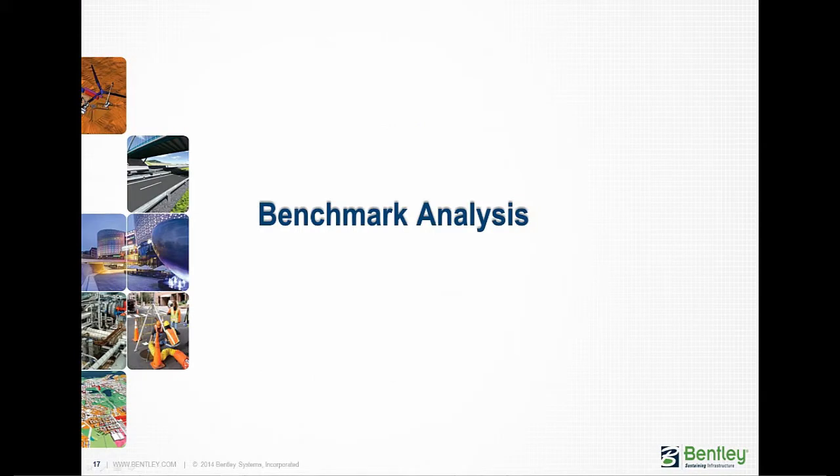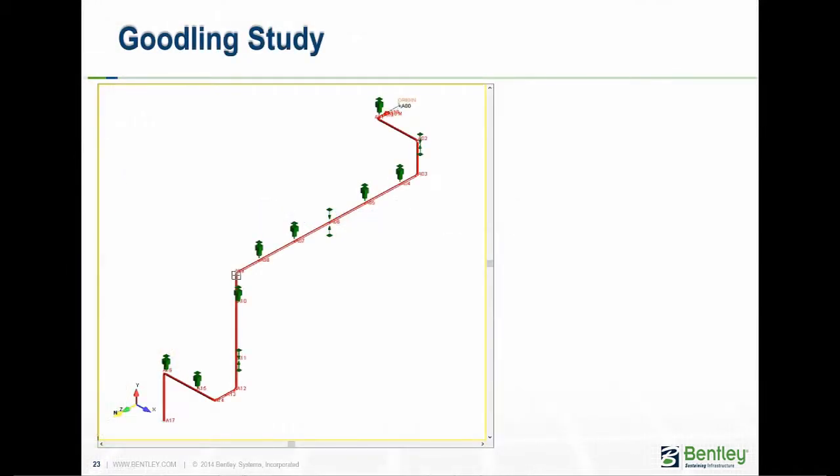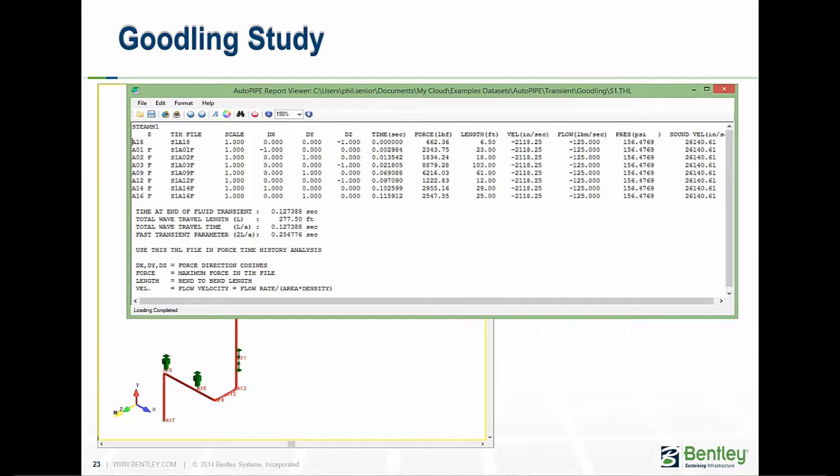In the early 80s, Goodlin investigated steam hammer in power generation plants. Whilst this flow condition was considered in nuclear plants, it was less common to do so in non-nuclear plants. Due to the large temperatures involved and the long lengths of main steam and reheat lines, large displacements were witnessed during turbine trips, of the order of 18 inches or 450 millimeters, due to transients caused by rapid closure of steam valves. He proposed a simplified approach to calculate the forces and displacements in the piping system that provides good correlation with the method adopted by AutoPIPE.